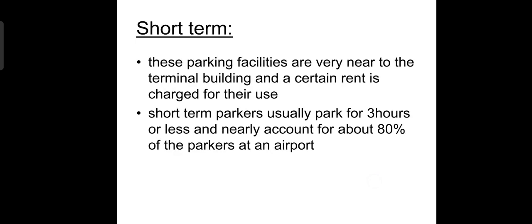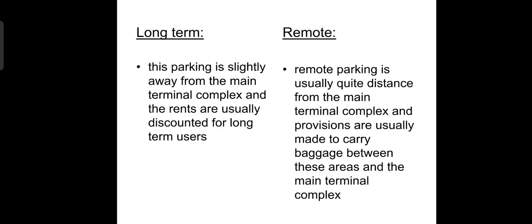Short term. These parking facilities are very near to the terminal building and a certain rent is charged for their use. Short term parkers usually park for 3 hours or less and account for about 80% of parkers at an airport. Long term. This parking is slightly away from the main terminal complex and rents are usually discounted for long term users. Remote. Remote parking is usually quite distant from the main terminal complex and provisions are usually made to carry baggage between these areas and the main terminal complex.